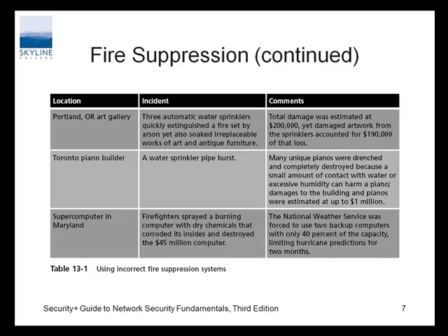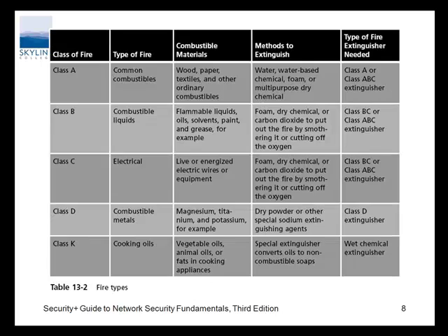A Class C extinguishing agent, generally that's CO2. Honestly, that's the one that's always been advertised as the thing you want to use for an electrical fire. But the first thing you want to do is get the power off, because then you've eliminated a lot of that. What you don't want to do is what these guys did here, spray it with a dry chemical, because the dry chemicals are extremely corrosive, and I think a lot of the portables around now are actually dry chemical extinguishers.